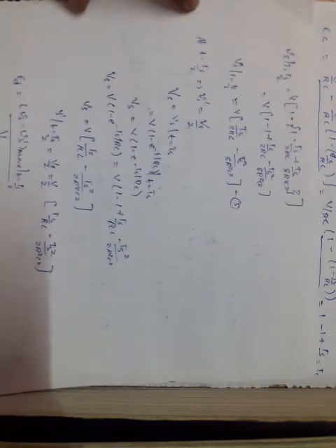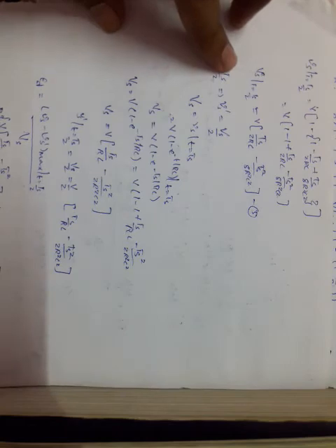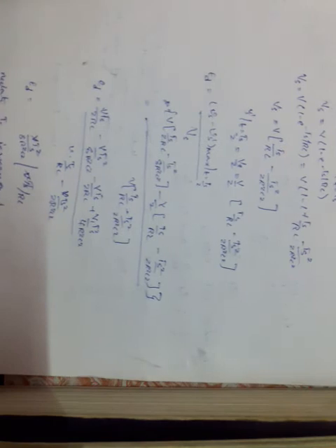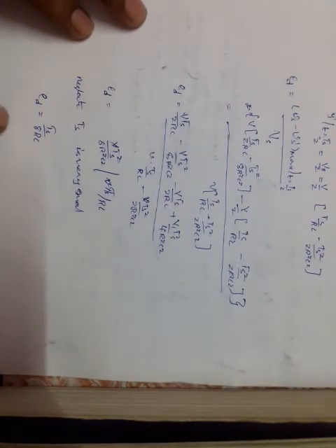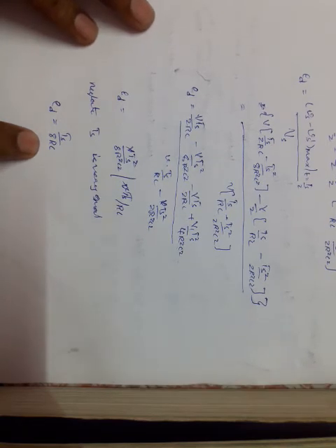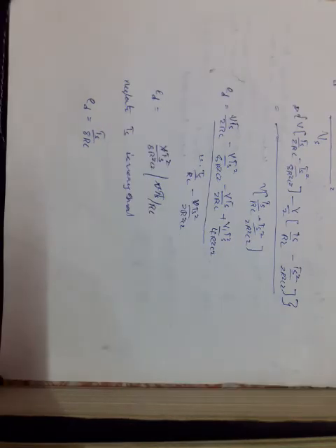After that, we substitute into the equations and calculate the value of displacement error. You have to substitute step by step and derive the equation. At last we will get Ed equal to Ts by 8 RC. Okay, Ts by 8 RC.